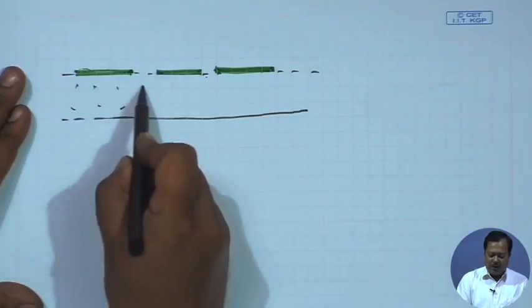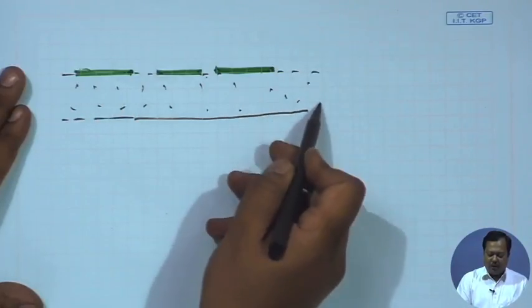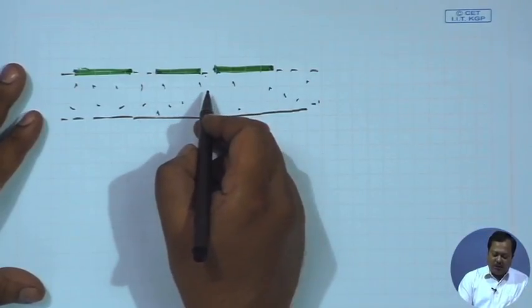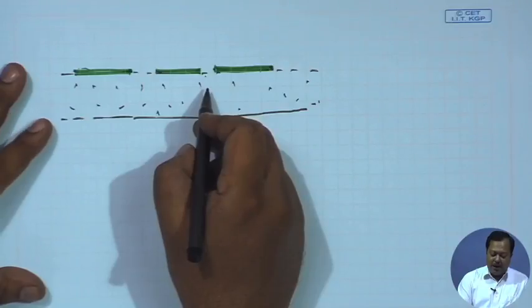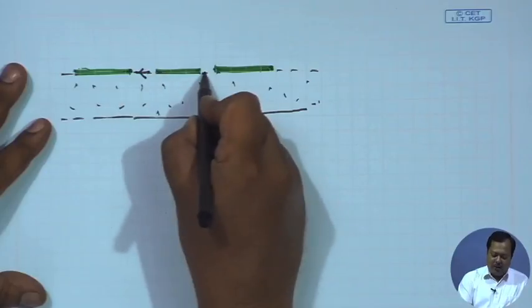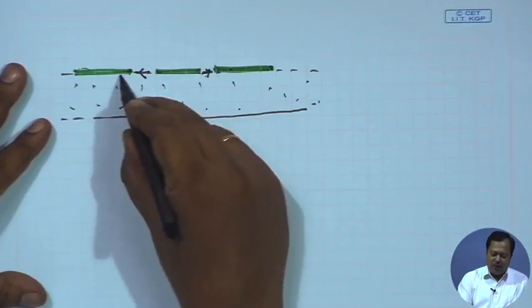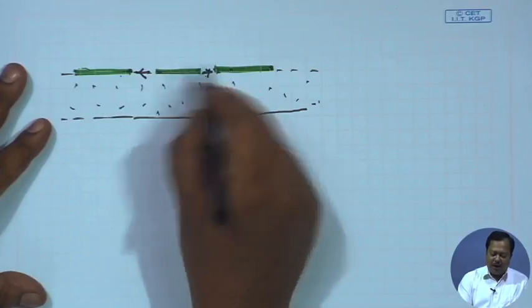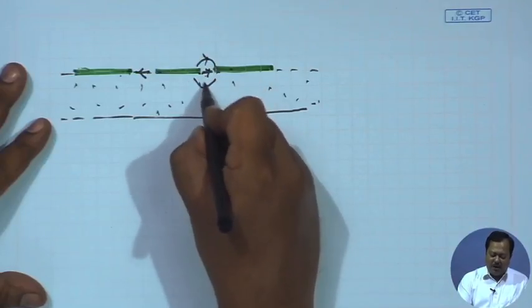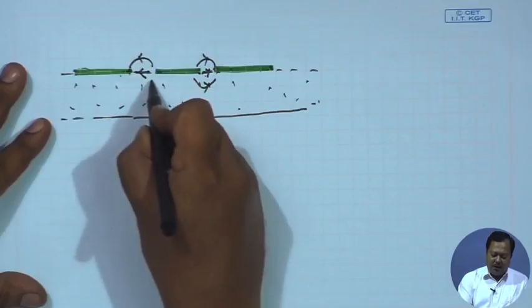You can consider it as a coupled slot. This is the cross sectional view. So, inside we have electric field. If you remember that odd mode and even mode excitation, we prefer even mode excitation, so that these two extreme grounds will be at same potential, and in that case the electric field configuration will be like this.